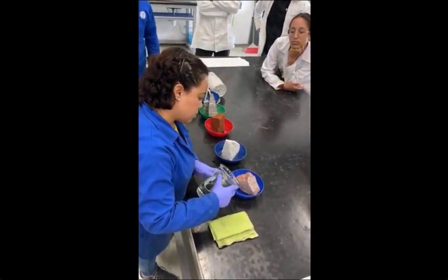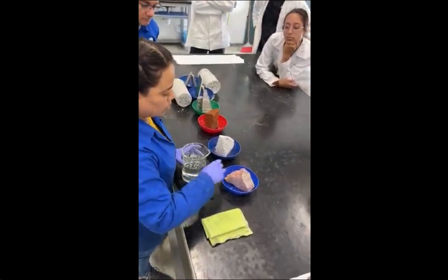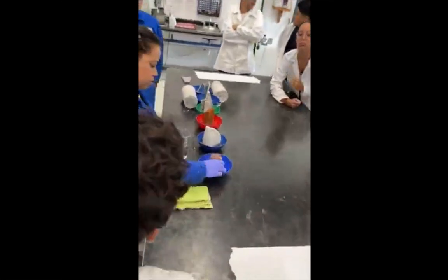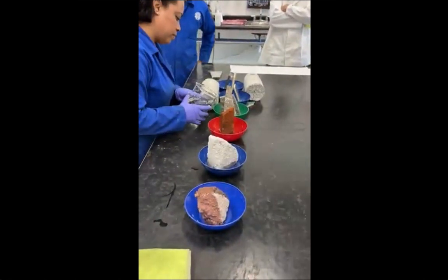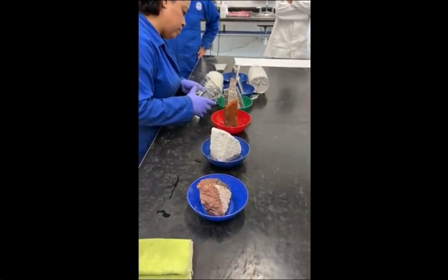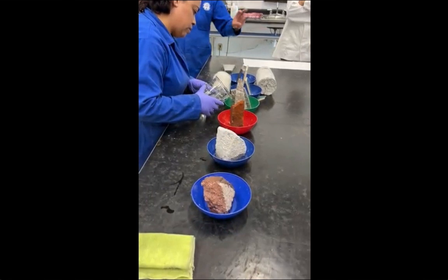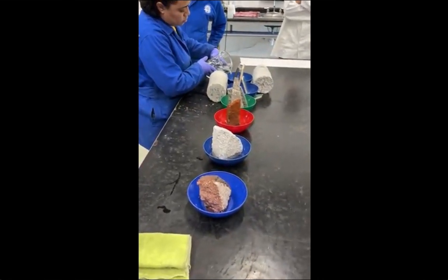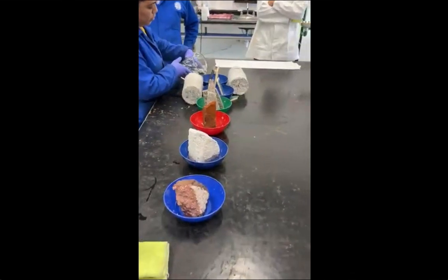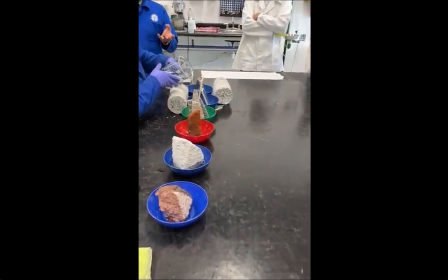And for the procedure, each of the ceramic pieces was kept in a plastic container for the experiment, enabling regulated exposure to the test solution. Then some sodium sulfate solution was poured into the bottom of each container. This chemical was used as a medium to simulate the ambient conditions that encourage salt absorption and efflorescence in ceramics.